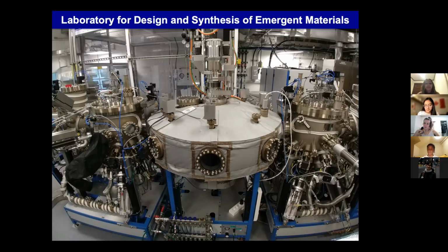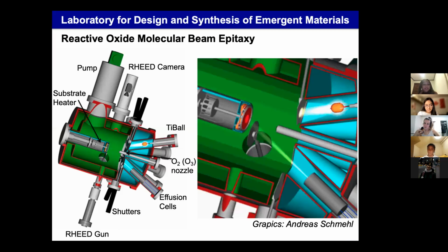I have a question about the RHEED system, or the MBE system. I think there's a slide where you have a diagram showing the different parts. So I understand the RHEED camera is to see if the layer has been deposited precisely. Do you have to continuously keep watching the camera throughout the growth, or check after each layer of deposition? Yeah, so we watch it continuously.